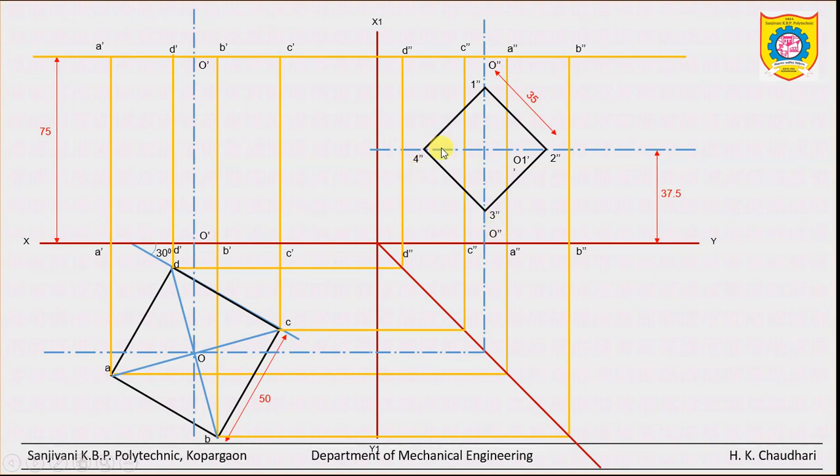Clear? Now just extend this axis horizontally in the front view, and 90 mm is the length of the horizontal axis of the horizontal prism. So draw the end projector here and on the right.